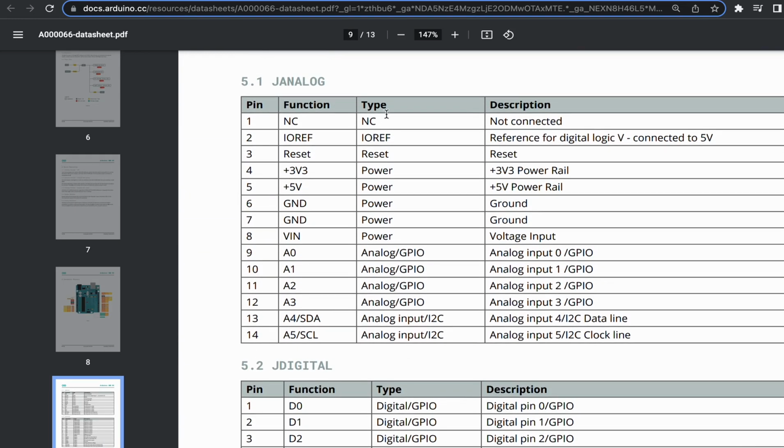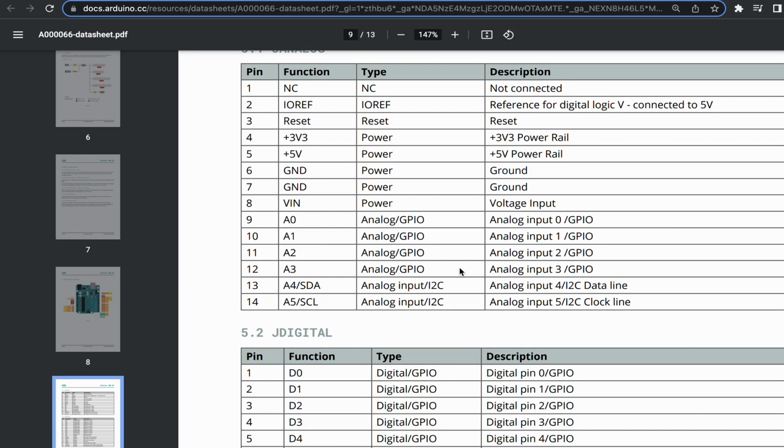We have the power section for it, 5 volts rail, ground, right? So if you want a device which is 5 volts, let's say a simple sensor which needs to be powered, we can give power through this. We have to first see the schematics of that particular IoT device and make the correct connection, or otherwise it would be a failure.